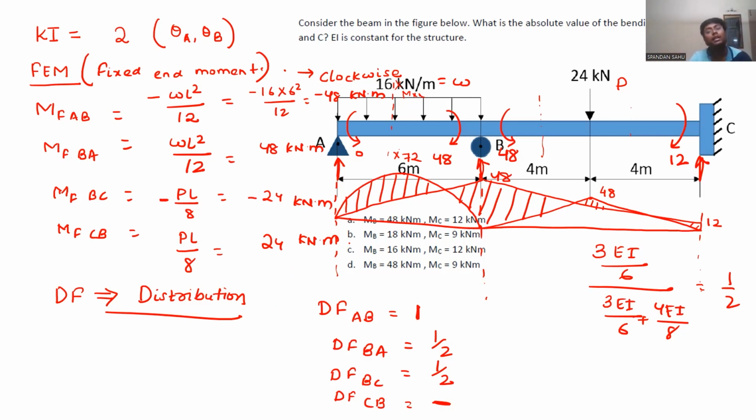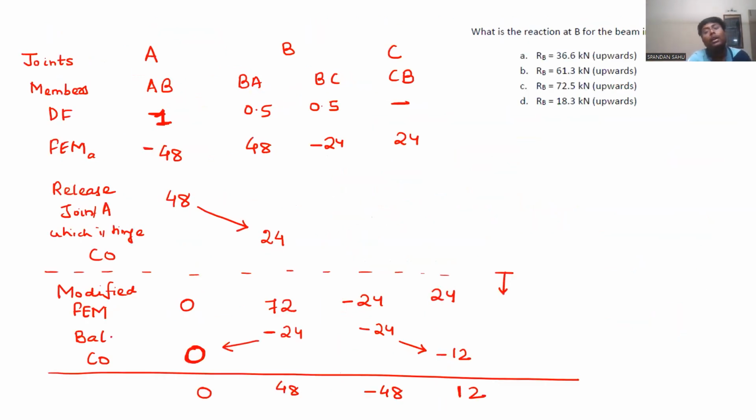Once reactions are done, it is like plotting the bending moment diagram for a simply supported beam, or a continuous beam where you know all those reactions. Just go on cutting section by section, write the bending moment equation for each section, and at each point where you need, get all those values, join that curve, and you will get your complete bending moment diagram in non-superimposed manner.